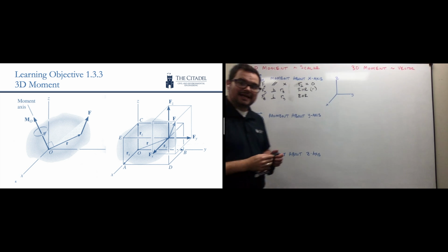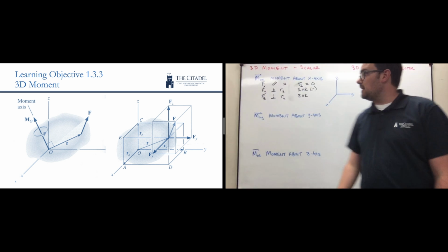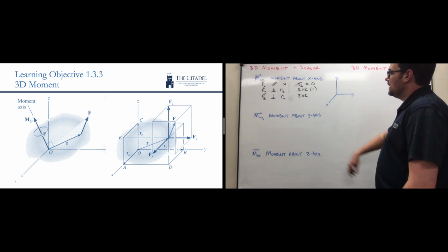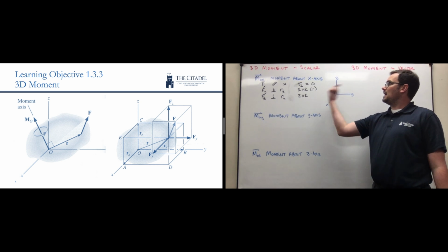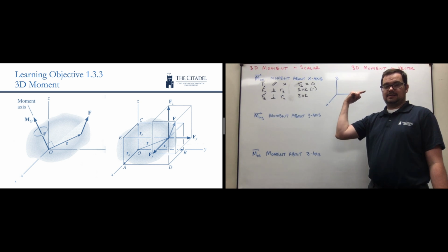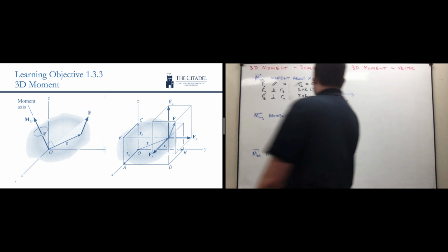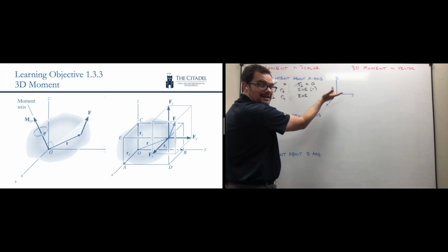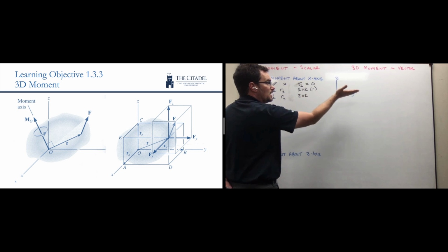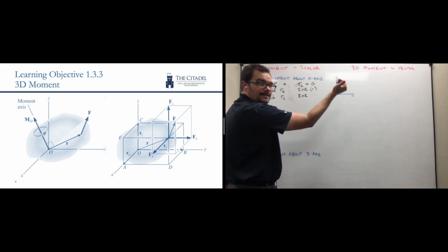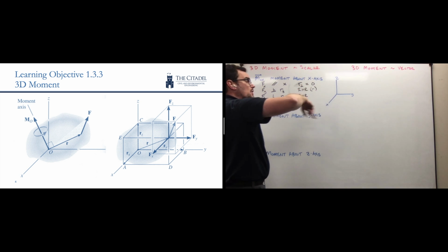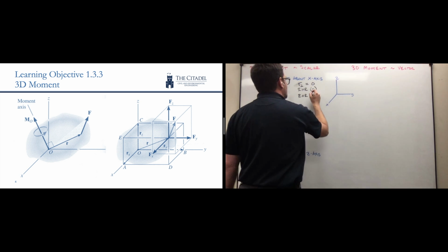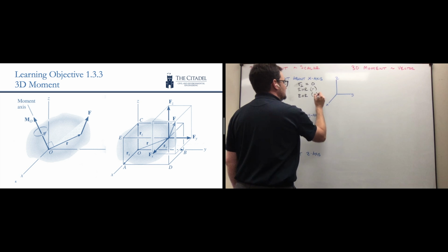Let's look at that. Okay, so we need R cross F, so Ry to the right, and then force Z is up, and then my thumb comes out of the board with my right-hand rule. Or I can do R cross F, thumb out of the board, and it's causing positive rotation about the x-axis, like so.